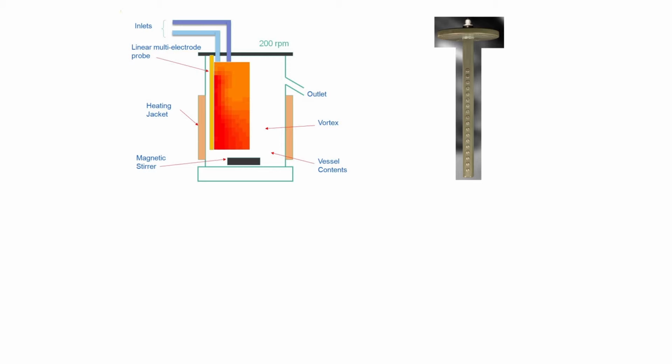We can increase the impeller to a higher speed of 300 revolutions per minute and derive a further image. We now see a modest vortex. Now a further increase to 400 revolutions per minute. We now see a deep and well-developed vortex. With further processing, we can use the data to specifically estimate the most likely location of the vortex boundary. We now see an unambiguous vortex location.